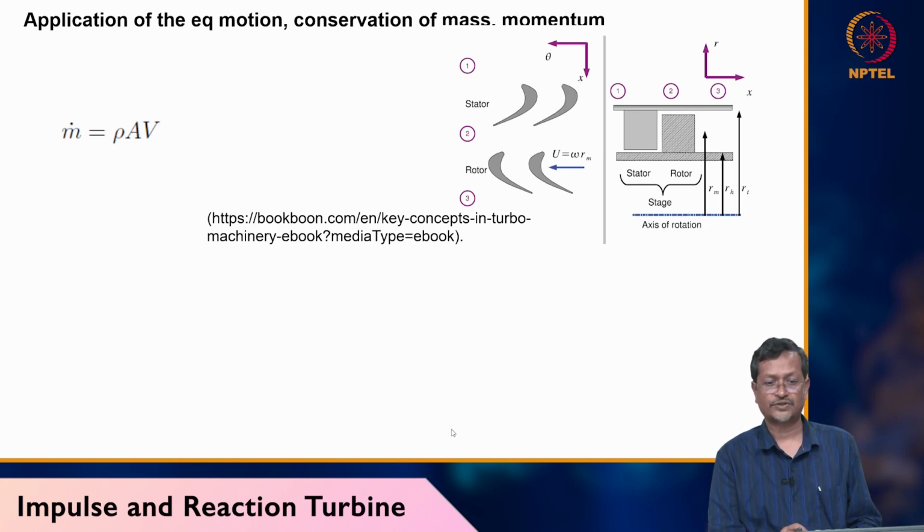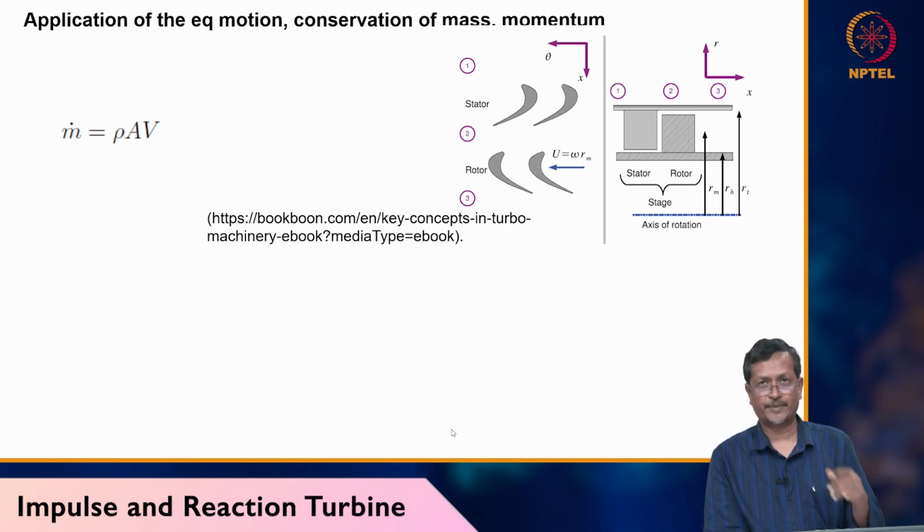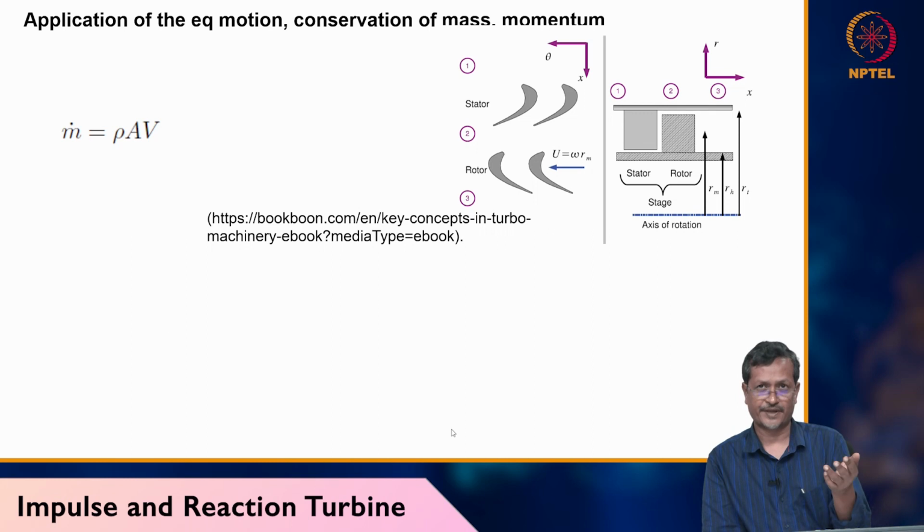Application of equations of motion: conservation of mass, momentum. Now whenever you are solving any fluid dynamics problem, you have to remember the mass conservation, momentum conservation, and energy conservation equations. If there is heat transfer happening, normally the energy conservation equation will be solved. If heat transfer is not there, normally we will be solving the momentum and mass conservation equations.